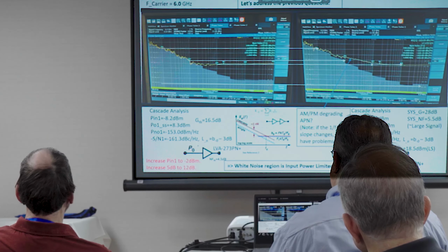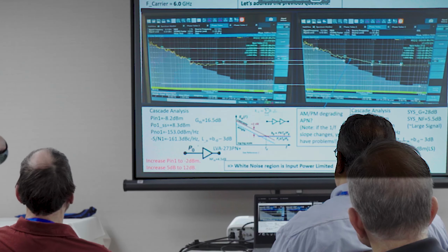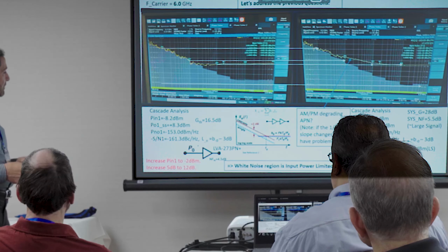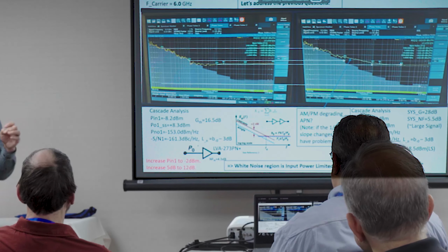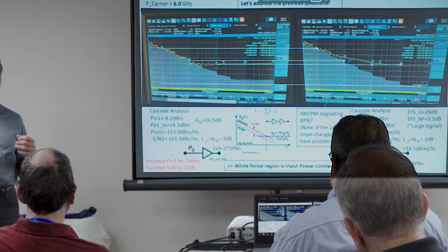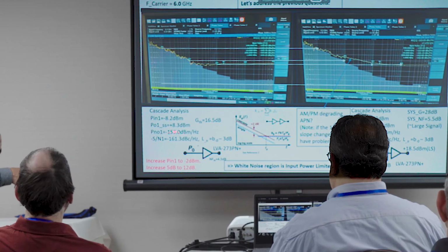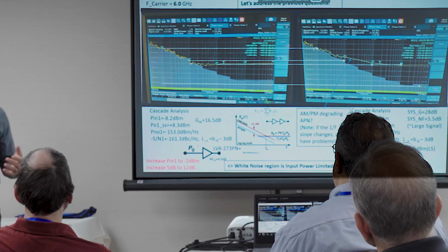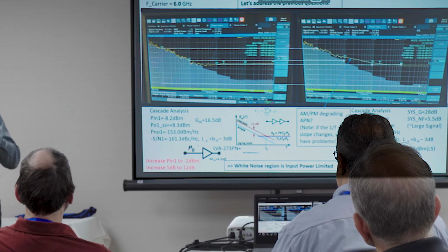These results are valid in small signal to a little compressed, but they're not really valid saturated, all right? But they are valid small signal to 1 dB or so compression. They're going to remain valid. So I calculate my output power. I calculate my noise output power, right? The minus 174 plus gain plus noise figure. I look at that at the output, one hertz bandwidth. If you're doing system design and cascade analysis, you already calculate this number. What you may not realize is that you're actually calculating the additive phase noise in the white noise region. You may know that, you may not.